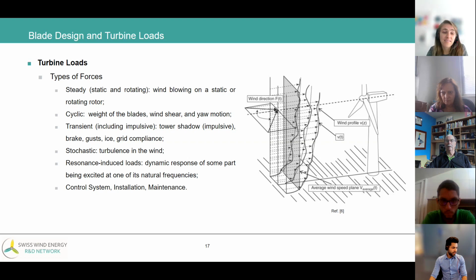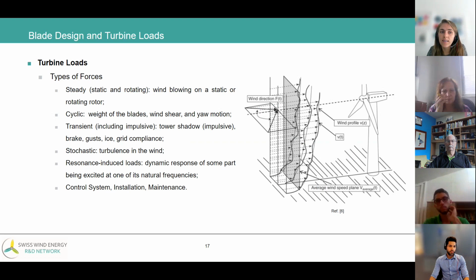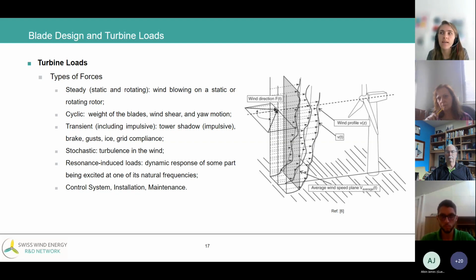But also, in the calculation of loads, the standard requires us to take into consideration a small deviation in the weight of each blade. It's a small factor that we always use. So if you have a small difference, your turbine will not go crazy. If you are within a certain tolerance, it's fine. Your turbine is prepared for that.